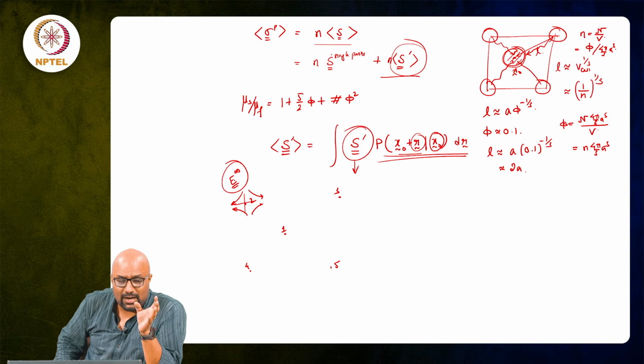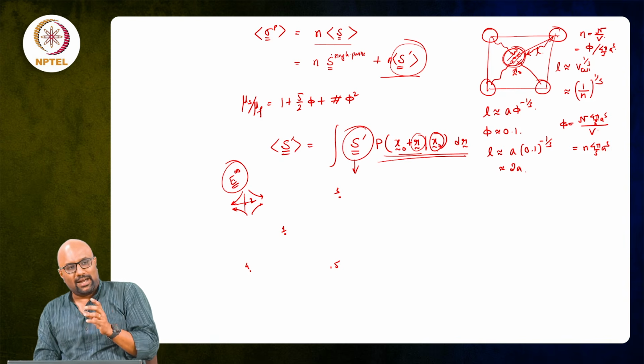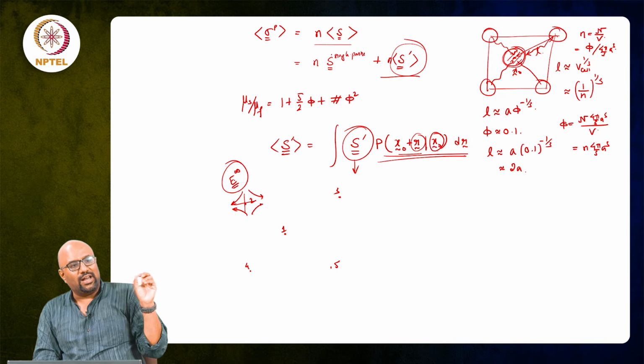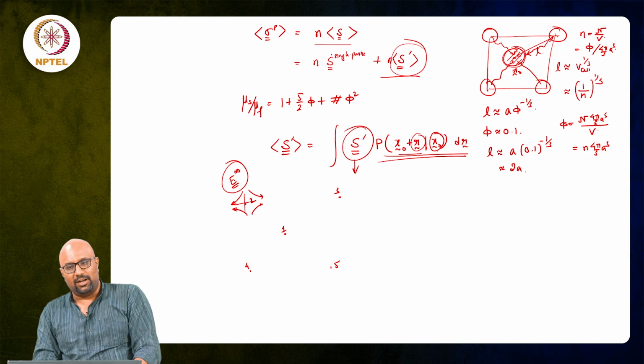Think of a single particle problem. Do not right now think of the 2 particle problem or interaction problem. Imagine sphere 2 in isolation. So, if sphere 2 is in isolation and it is present in a linear flow which has a straining part, that is E infinity, will it create a disturbance if it is force free and torque free? Yes, it will, right? Why? Because it has to resist the rigidity. It has to maintain its rigidity, it cannot deform.